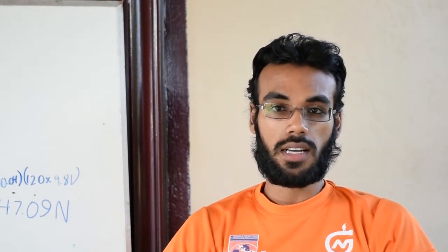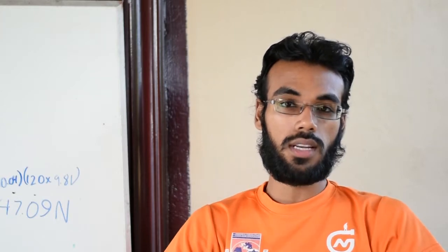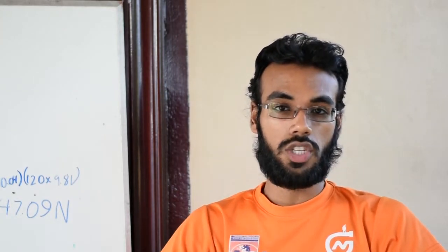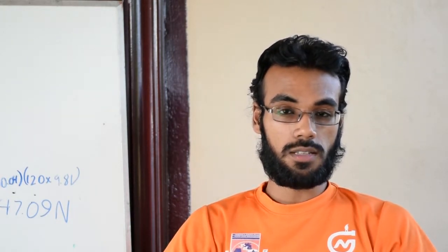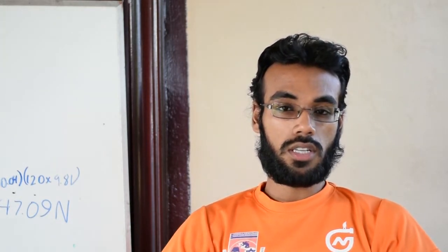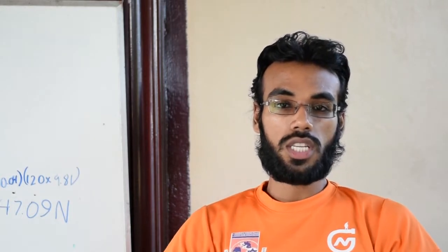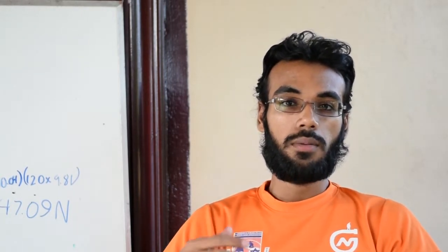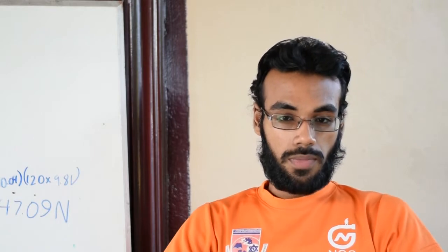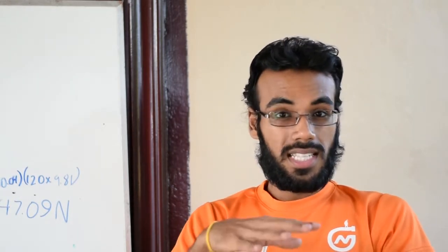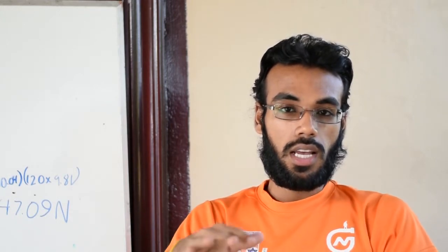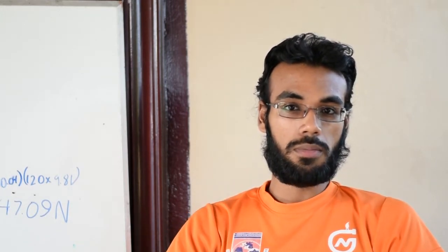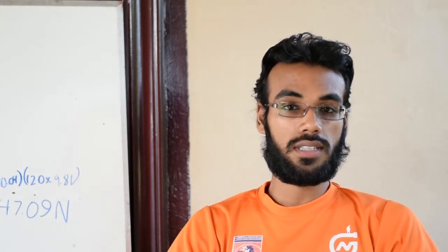Our hovercraft, in essence, involves a piece of plywood with a hole in the center, a leaf blower as our engine to push air through into a skirt beneath it. The skirt that we made is made out of tarpaulin. In our skirt, we also have small holes at the bottom which allow air to flow through, which prevents any bursting of the tarpaulin. However, the basic principle is the same, because in that skirt that we built under our plywood, there's a high pressure maintained there such that there's distance off the ground from the skirt, and the hovercraft itself is able to travel.